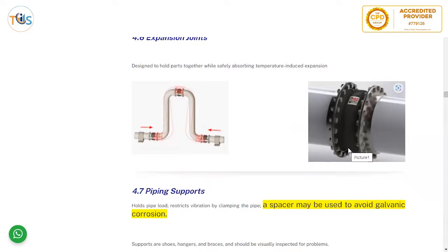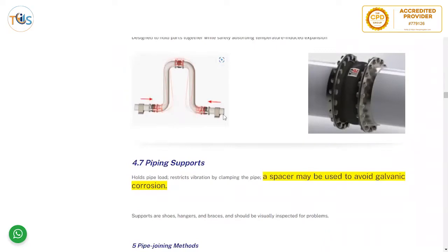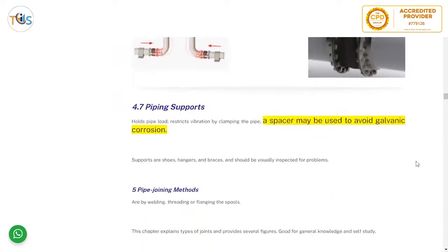contract without putting a lot of stress on the pipe joints or the pipe itself, to compensate for that coefficient of thermal expansion. I mean, it's normal that for every 100 feet, if you have a 300 degree Fahrenheit change in temperature, you have 2-3 inches of expansion, and that 2-3 inches needs to be accommodated. That is done by expansion joints, which are normally of two types. This one is not very high pressure, so you can use a rubber one. This is for high pressure pipes, and it's more reliable, the U type.